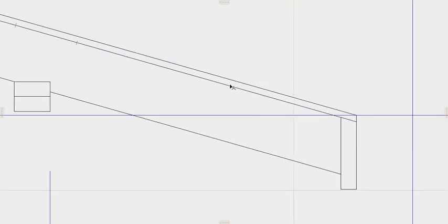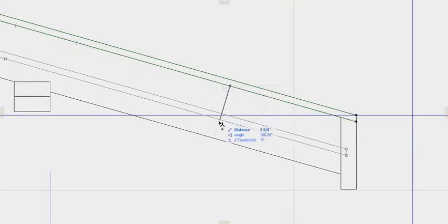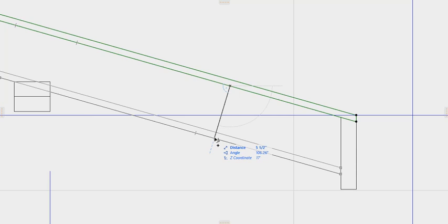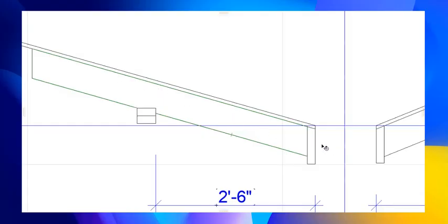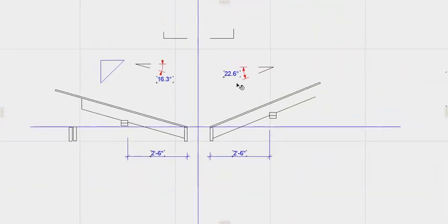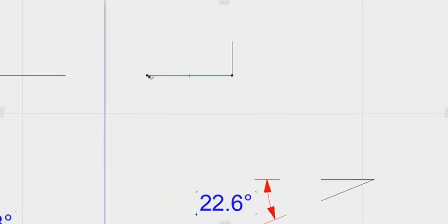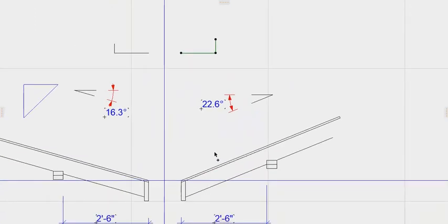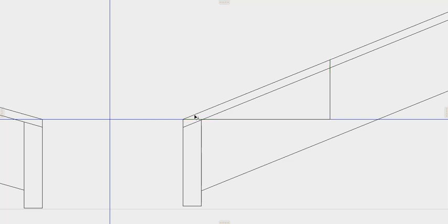And then you take another line, and in my case it'd be about 5.5 inches, whatever your rafter is going to be. And now you've established the rafter. Okay. Then on the other side you want to do the same thing. So I've got a little 12 inches here and 5 inches there, and that is how I establish my pitch.